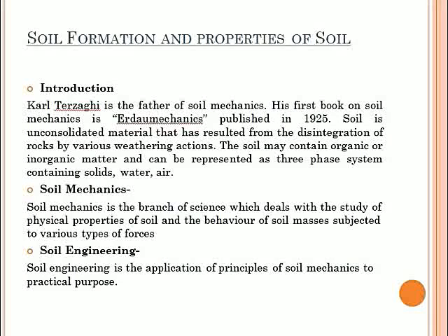His first book on soil mechanics, Erdbaumechanik, was published in 1925. Soil is nothing but the unconsolidated material that has resulted from disintegration of rocks by various weathering actions, such as physical or chemical actions. The soil may contain organic or inorganic matter and can be represented in a three-phase system diagram, which contains solid particles, water particles, and air particles.